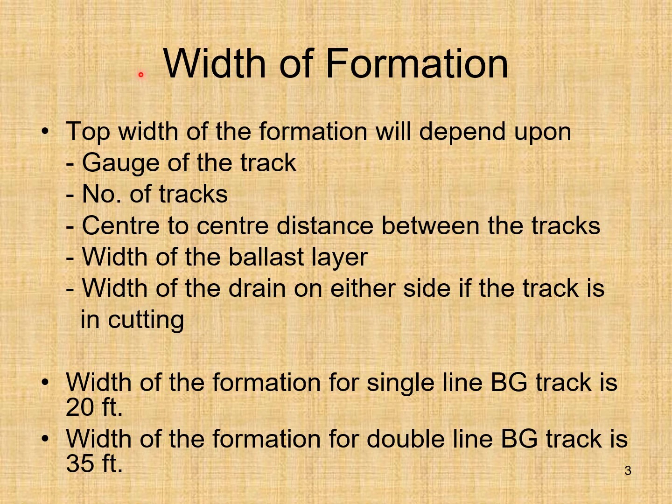Widths of formation. Top width of the formation will depend upon the gauge of the track, number of tracks, center to center distance between the tracks, width of the ballast layer, and width of the drain on either side if the track is in cutting.